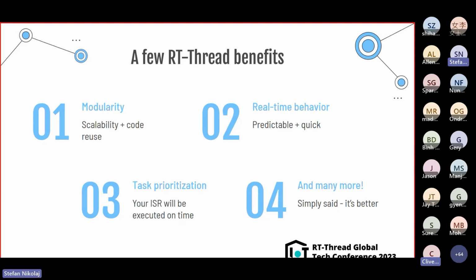And finally, one third important feature of real-time operating systems: task prioritization and interrupt handling. So you program an interrupt from a circuit which signals that your PLC is on fire and you need to shut down everything or else the building will burn down. And the interrupt is then interrupted by an unrelated ISR. Maybe the UART circuit received a message. Your save-the-building routine is now interrupted.